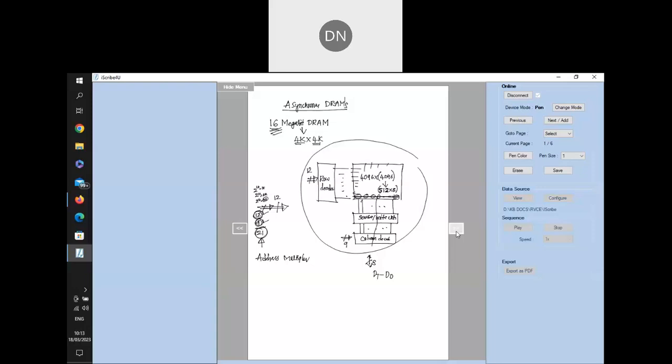Now what I will do is, first I will send the row address. I will copy that somewhere, because I am using the same address lines to send the column address later. Since I will be losing the address, I have to keep it somewhere, so I'll use a latch. We know a latch is the one which stores it. Since this latch stores the row address, it's called the row address latch.